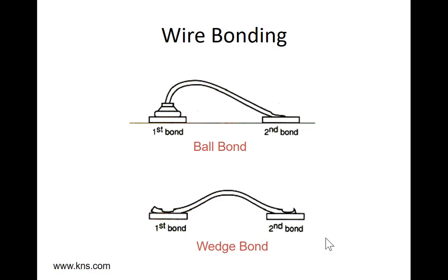Here's kind of how it looks if you do wire bonding. You put a wire ball down on the die and you smash it down. So it's warm and you put pressure to it, and gold is malleable. It kind of bends and so that ball gets deformed and it looks something like this. It's hot and it sticks. Then you slide it over here, go down and push it on the package and push hard, maybe wiggle a little bit, it sticks again, and then break it off there and you've got your bond. If there's 400 pads, you do that 400 times on one die.